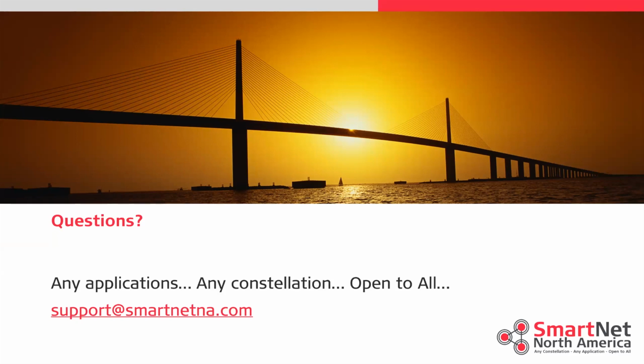CSRS-PPP is adopting 7.0 while we match 7.1 on SmartNet? Yes. So CSRS-PPP, that's the NRCan PPP solution, basically NRCan's OPUS for guys in the US. They're currently on 7.0. They will adopt 7.1 in January, so we'll be a little bit ahead of the curve just because it aligns better with the timing of everything. But yes, it'll match up.